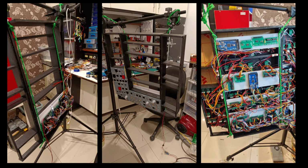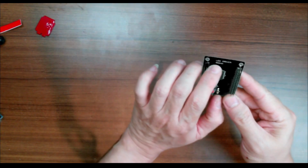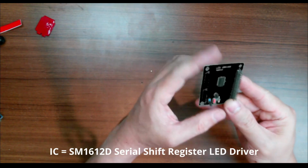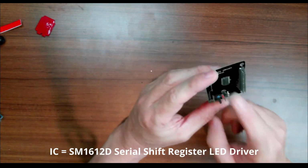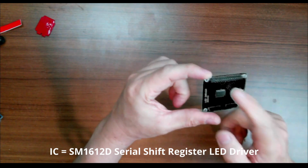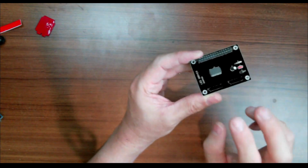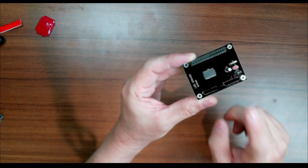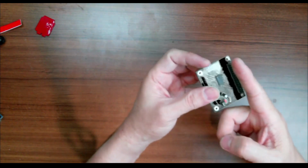Once you use that, you can drive any LED. I'm also using a special chip I designed myself. I forgot the chip, it's called SM16126 or similar. This is an LED driver chip. It's very convenient because this small SMD chip can drive 16 LEDs on this small board. You can just use a shift register with serial input, but the output is parallel.